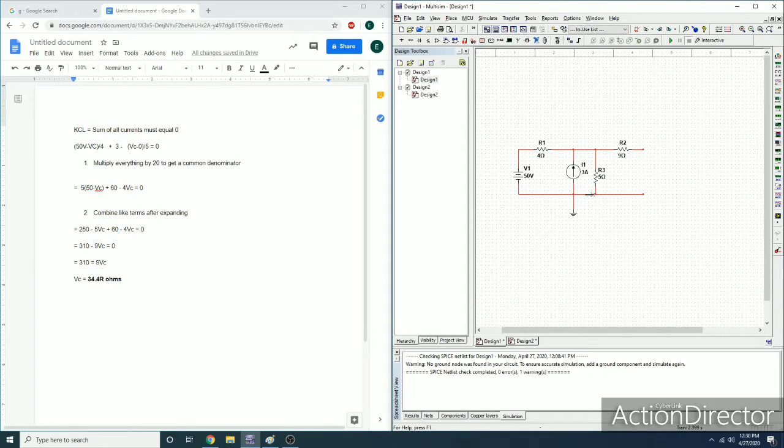We can bring the circuit back to normal, and the next step is to find V Thevenin, the equivalent voltage. To do that we can use the combination of Kirchhoff's current law and nodal analysis to find our answer. Nodal analysis, or Kirchhoff's current law, states that the sum of all currents going in must equal 0. We can use nodal analysis and KCL to help us find this.